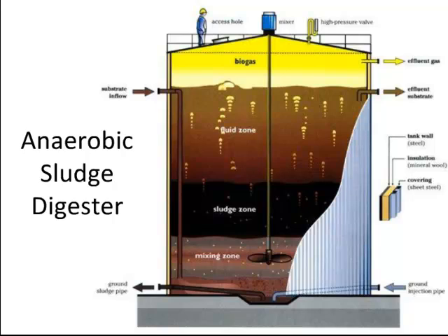So the sludge is collected and pumped down pipes into an anaerobic digester. There it's heated up, it's warmed up, and bacteria are added, and the bacteria break that sludge down. They break the sludge down to types of alcohol, and then other bacteria break those types of alcohol down into methane. So bubbling up through the sludge, we get methane that can be collected.